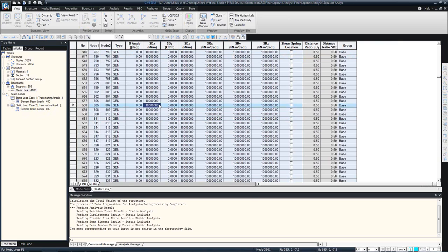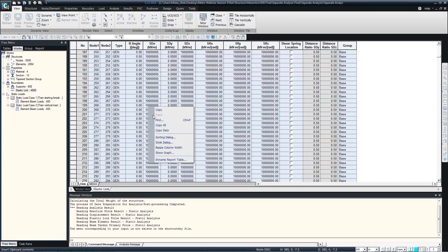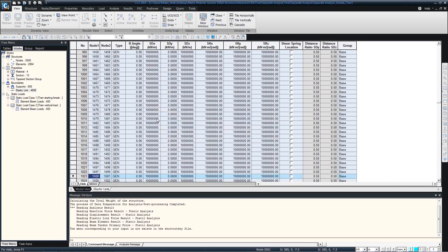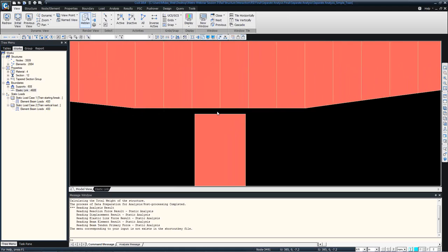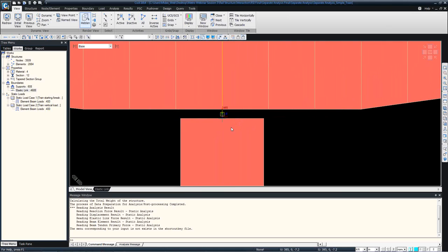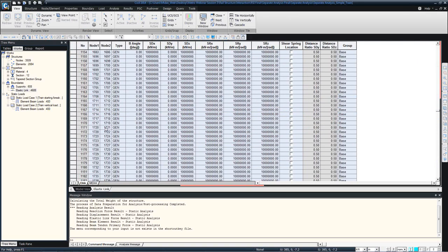Okay, so if you go to the elastic link properties, second. You can change all these properties according to your will. For the bearing properties also, you can find what elastic link is there. Between nodes, you can just check what nodes are there: 3492 and 3501. So you can go to the respective elastic link. You can also display the number of the elastic link, so it depends upon the user what number he is using.